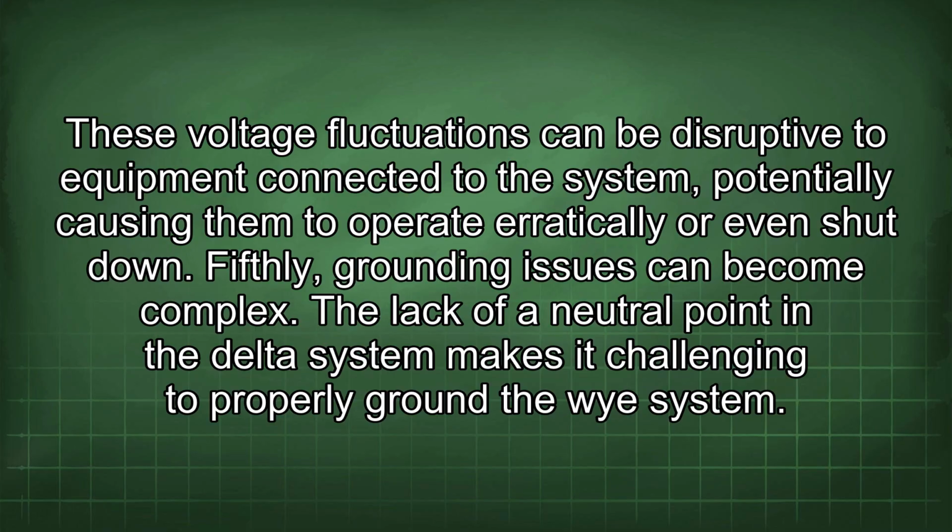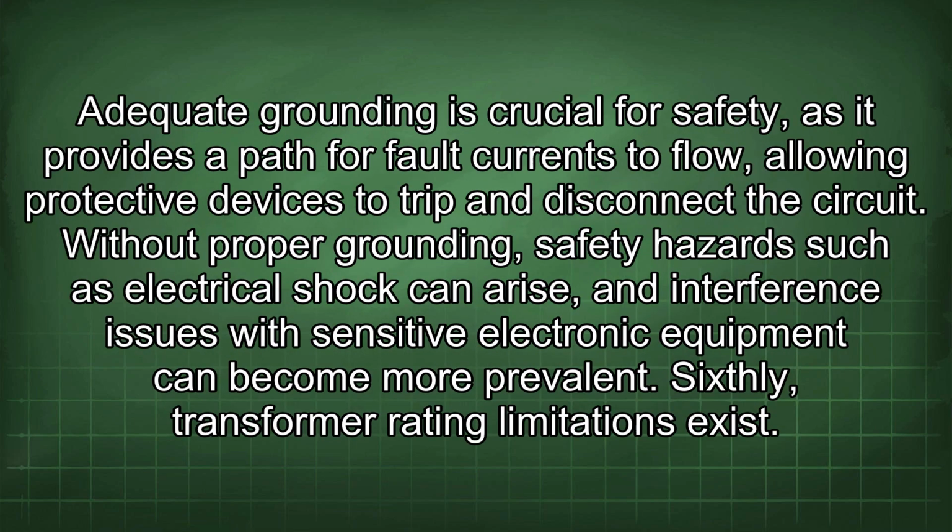Fifthly, grounding issues can become complex. The lack of a neutral point in the delta system makes it challenging to properly ground the Y system. Adequate grounding is crucial for safety, as it provides a path for fault currents to flow, allowing protective devices to trip and disconnect the circuit.